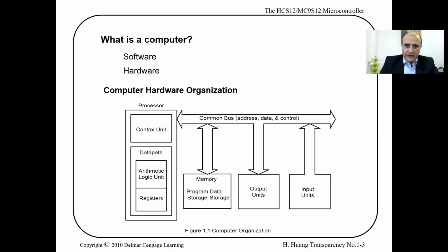Okay, so we start. We spent a lot of time here. We talked mainly here. You need to remember that we have a program memory that is non-volatile, usually flash memory in microcontrollers, to put our program at, and data memory, which is usually two types: EEPROM for non-volatile memory for data, permanent data, and SRAM that is volatile and for temporary data.